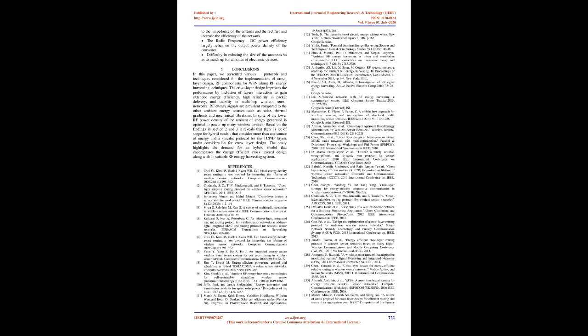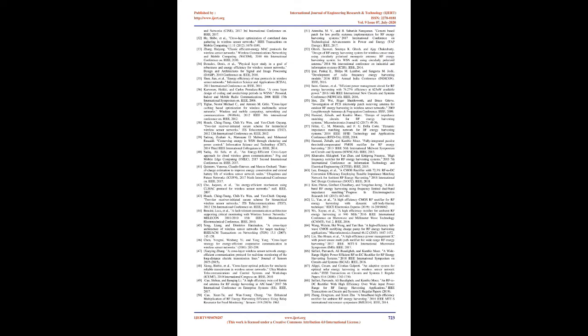Kim et al. 2019 proposed a power generating scheme using a CMOS intercoupled RF energy rectifier that increases energy efficiency by decreasing reverse saturation current. The rectifier is fabricated with 0.18 µm CMOS technology for UHF band applications to gain a maximum PCE of 75% for 1 V output voltage, and also claims to have improved PCE by 8.8% over the existing rectifier circuits.